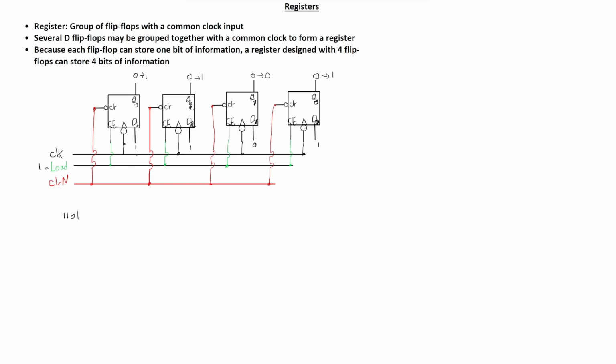So if we give any other inputs, let's say we give it an input of 0011, this will not change what's stored in this register because load is disabled. Remember, we enabled it for just 1 clock period. So if we have a signal like this, for 1 clock period from here to here we enabled the load. So the load became 1, and after this we disable it. During this time, we loaded 1101. If at any point later we enter any data to the flip-flops, this will not change what's stored in it